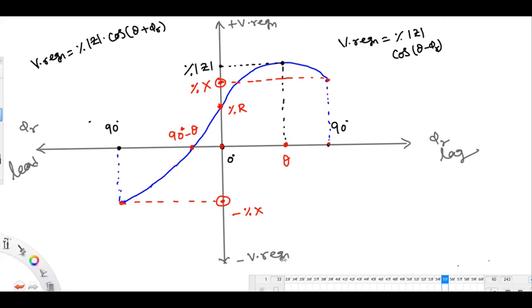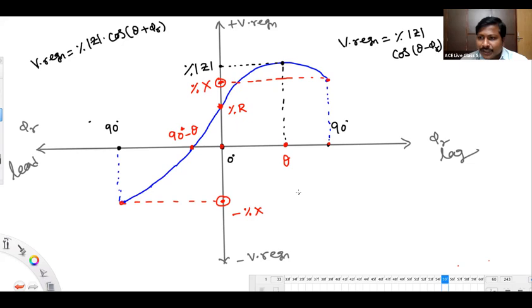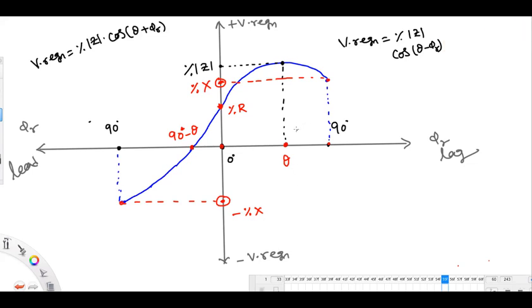Sir, in a primary distribution system, whether neutral is required or not, sir? That depends upon their requirement actually. If you are giving a direct 11 kV supply and they have their own transformer, you don't need to supply the neutral. Means it is not necessary, sir. Not necessary.